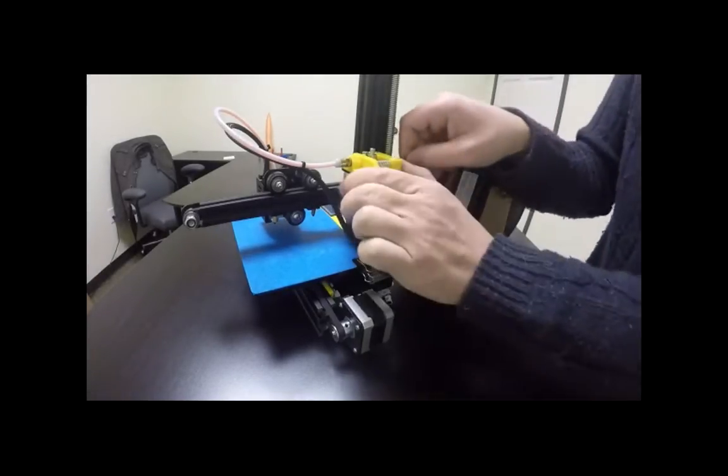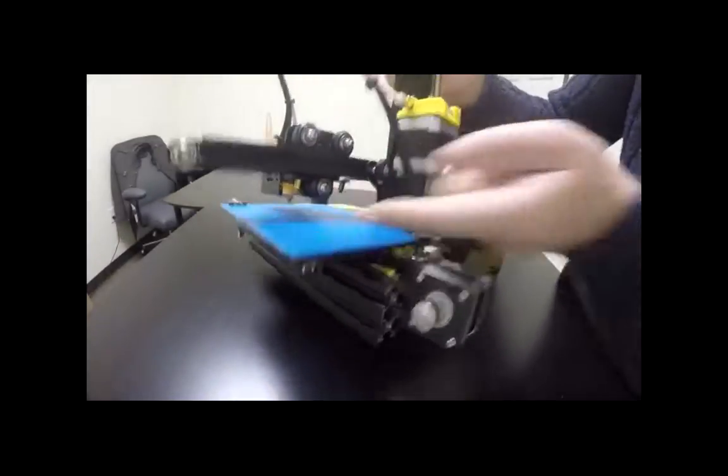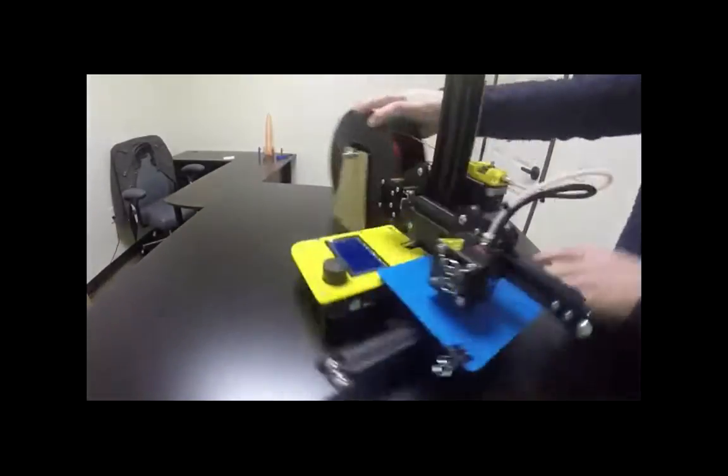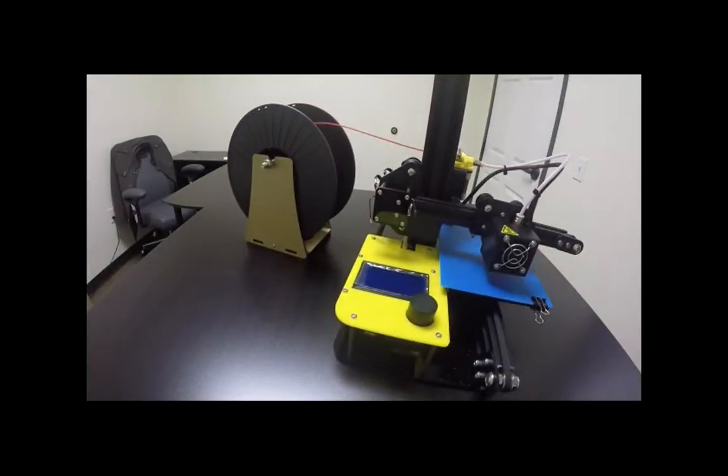So then when it gets heated all the way up, just push some more filament through, and then when you see some coming out of the end, right there, then let me know and we can move on to the next step. We're at 187. 188. It's at 187. You pick it out. No, 190. You got to push it through. 190 pushes through. Yeah, see if it comes.